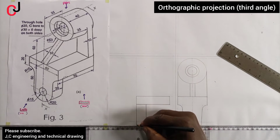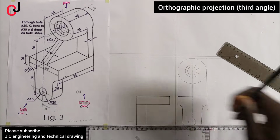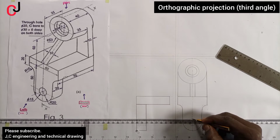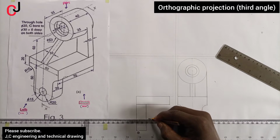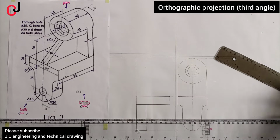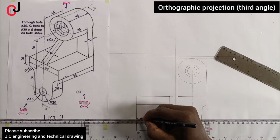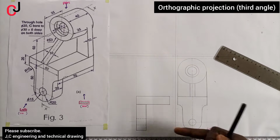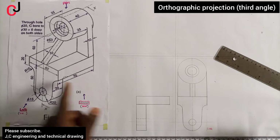Once it hits the front view image, you indicate it with a broken line, indicating that there's a passage there. Do the same to the top of the circle. Once it reaches our front view image, you indicate it with a broken line. Now, this indicates that there's a hole passing through while looking at it from your front view.